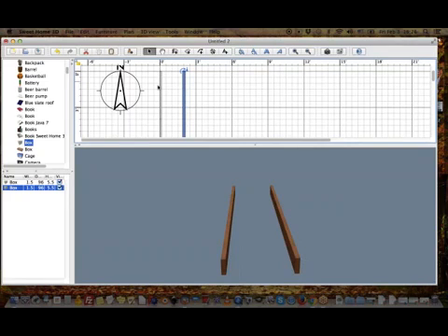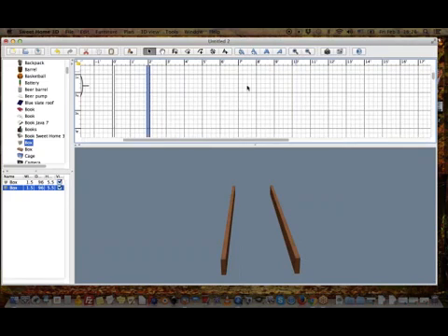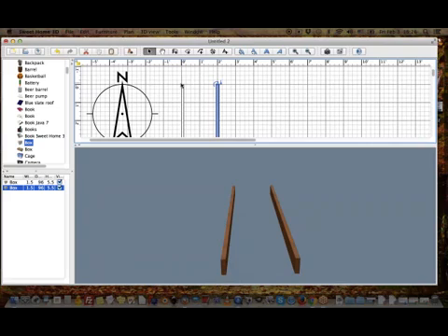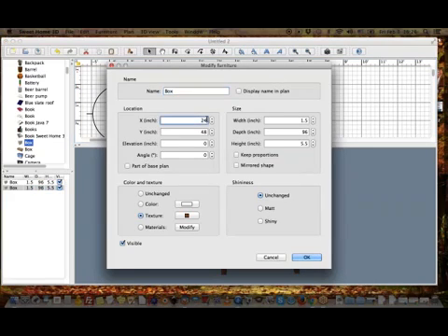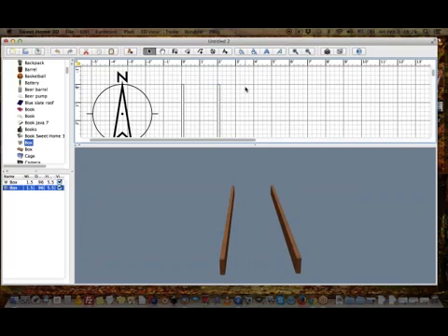Except that what Sweet Home 3D is doing here is that it's 24 inches from this point to the middle of this one. But what I actually want for 24-inch on center building is for 24 inches between the center of this one and the center of this one. So what I'm going to do is I'm going to add 3/4 of an inch to this. And now I know that there are 24.